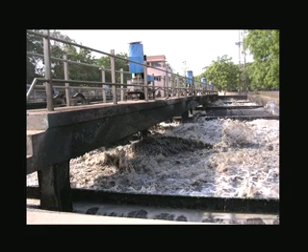This shows a surface aerator. We can see this is the surface aerator and the water is getting mixed thoroughly here. The turbulence here is much higher compared to the plug flow or diffused aerator. So, here good mixing is taking place, and oxygen transfer is also taking place. In any activated sludge aeration tank, we provide a series of aerators.